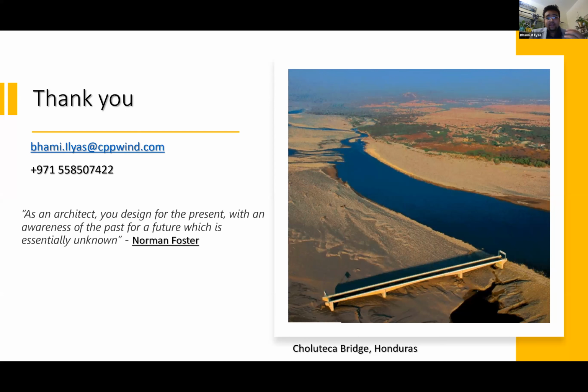One of the basics, a rule of thumb, is that somewhere around 25 to 30 stories, your building is sitting on the fence, where you can go with a code provision versus a wind tunnel. As the building gets taller, the wind actually governs your design, and then you have to take into account different damping criteria that come into play. It's a function of your architecture and the dynamic properties from the structural engineer. Then we make an assessment based on that.